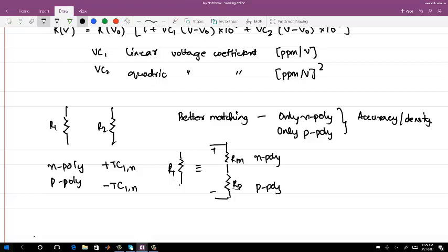So if you are going to use any kind of resistance in a loop filter, you look for what all kinds of resistance exist. What is the parasitic capacitance for each resistance, because you do not want to add a lot of capacitance. How much is the percentage variation in this particular capacitance across the temperature and voltage which you are going to use. So all those things you look for, and then you go and select one. Okay.